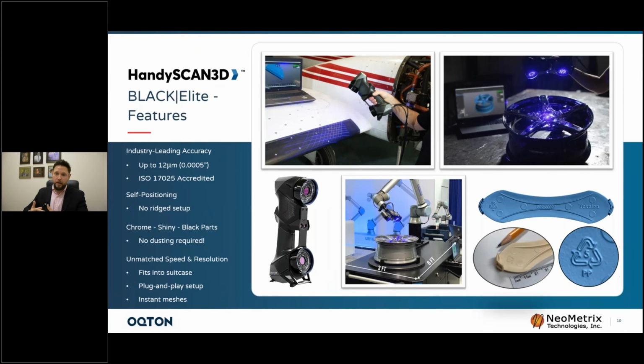A little more information on the HandyScan. We have models that go up to 12 microns, or 5/10,000ths of an inch. So you're talking very high fidelity, highly accurate data that we can use for metrology circumstances. Each one of those triangle points is accurate, with that single point accuracy. We're also ISO 17025 accredited, which is really exciting and unique. If you're looking at one of these to service as many customers as possible, having that is very important to make sure you're up to their standards and you can prove out your accuracy, repeatability and traceability as well.